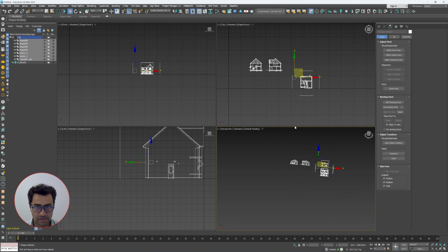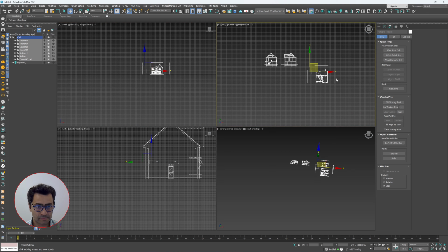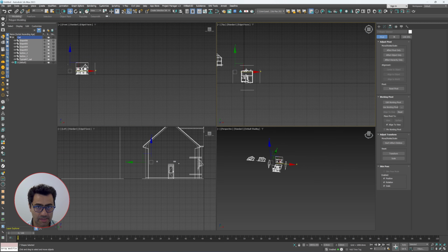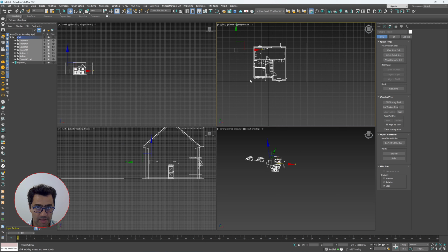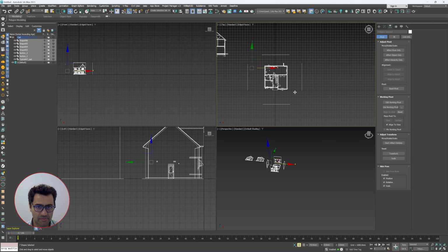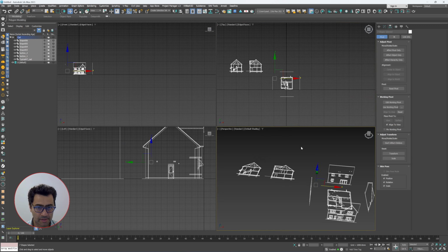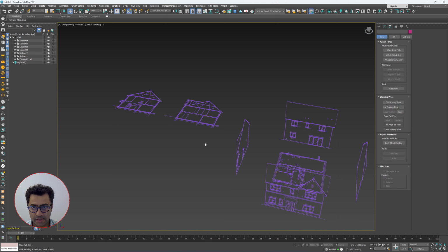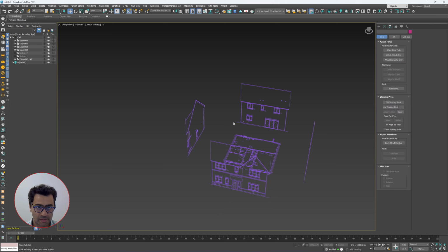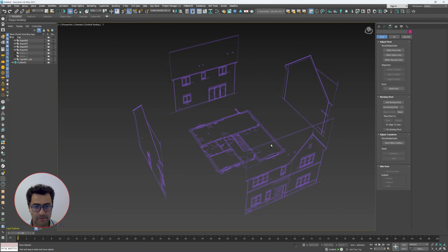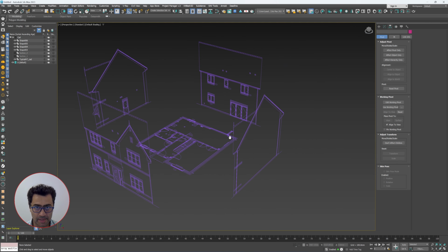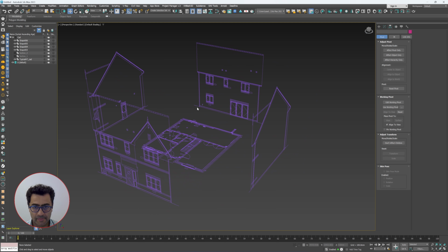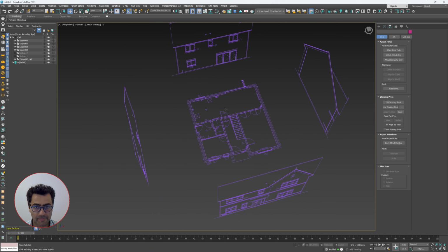The other bit you need to make sure is you can then move these drawings to roughly the central area here. Once you've done that, then just disable section drawings for the time being so that we can actually concentrate on just the bits that are needed. Okay, so let's get started.